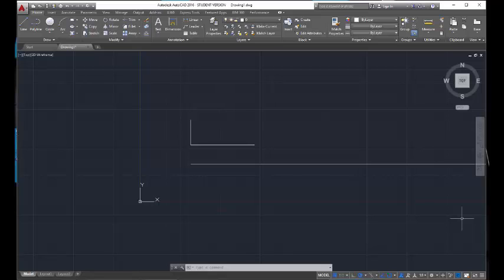So just to recap on this video, if you encounter a line that shoots off the screen, don't panic. Realize that the zoom of that line is simply too small for the object, and you need to adjust your zoom for a better fit. When that happens, I usually use the zoom extents or the zoom all. Now if you need to concentrate in a small area of your drawing, I would recommend using the zoom in or the zoom window tool.